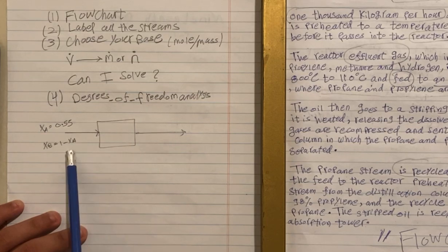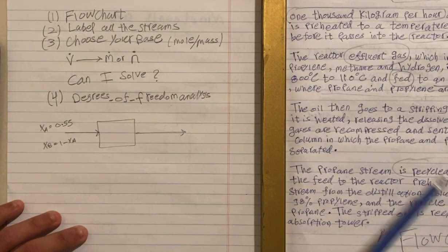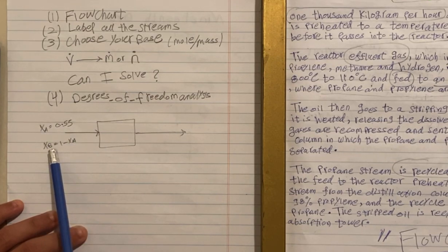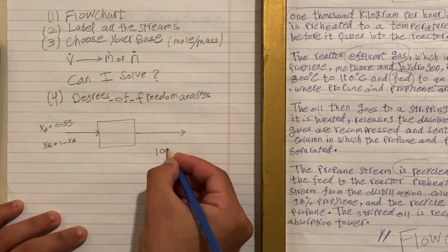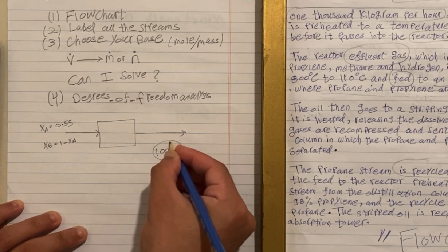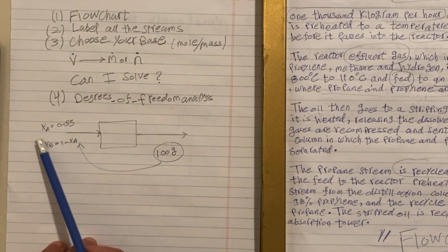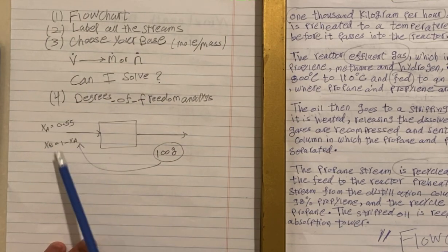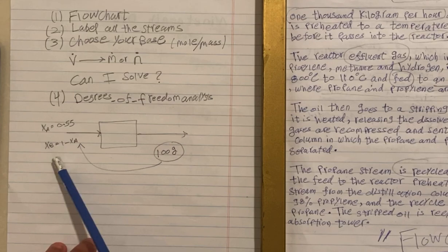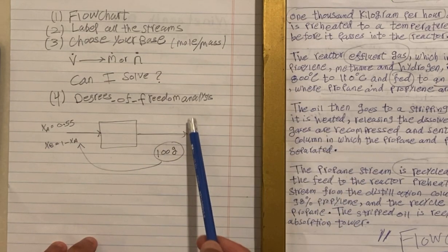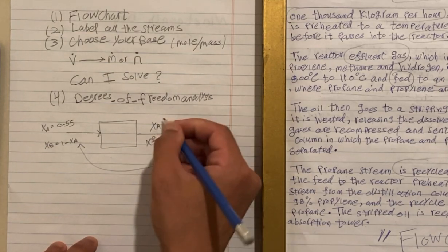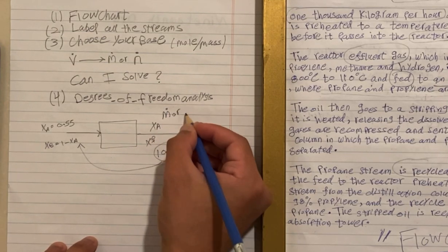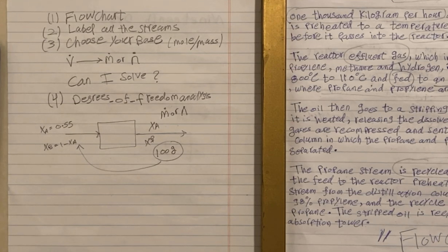In both the streams you don't have the mass flow rate or the molar flow rate or even the volumetric flow rate, but here you have a composition, while here you don't have any composition. So if you choose a certain base like 100 gram, then you should put this 100 gram in the stream. You can find their flow rate, the component flow rate of A and B, and this will help you later on, as we will see, how to calculate the flow rate of A, the flow rate of B here, and the composition.